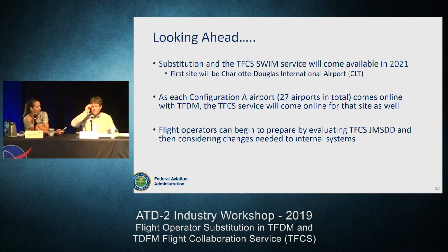Is flight substitution limited to the flights going to the same runway? No, they just have to be part of the same program. So if you're running a runway-only SMP, and two airplanes are going to different runways and one's not part of that runway SMP, then it can't be substituted. But as long as they're part of the same SMP, that's the crucial data piece.